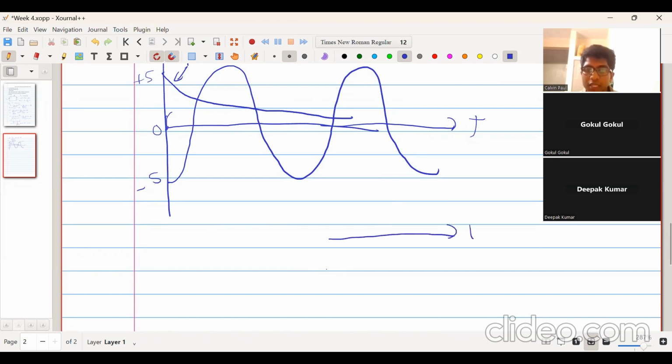We will assume the supply phasor to be like this. This is the supply phasor, and we know that the current lags, so the inductor current will lag it by an angle theta. Phasor means it is not just a constant vector value; it keeps on changing, that is, it keeps rotating in the counter clockwise direction at an angular speed of omega. That is what is known as a phasor. The inductor current also is not fixed at a position. It will also keep rotating at the same angular speed omega, but it will have a constant lag of theta degrees with respect to the supply voltage.